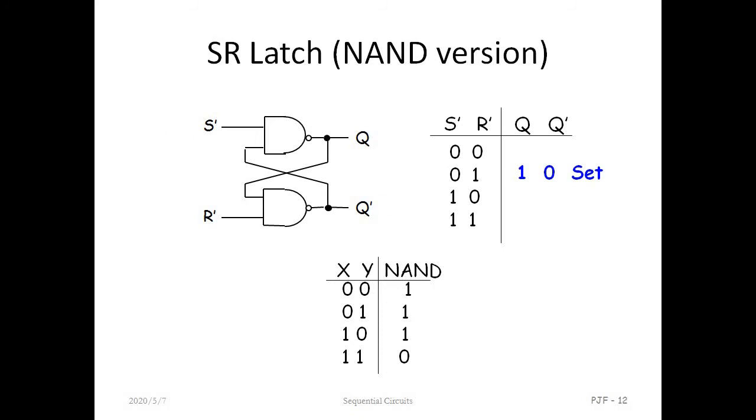Second case, this is very important. Generally students get confused. What is the condition for 1 1? Generally this condition is called the memory condition, because a sequential circuit always considers a memory element. In 1 1, what is the value of Q and Q bar? When you see the previous state, 1 is always stored, that is Q is 1. So here Q is 1.